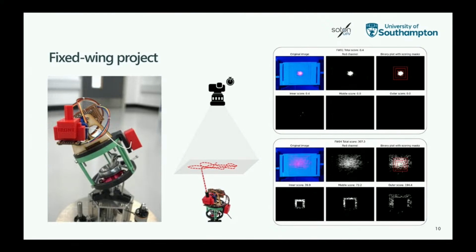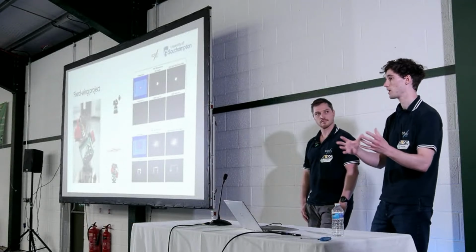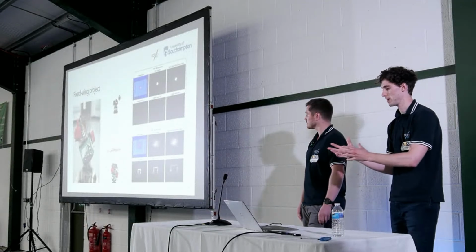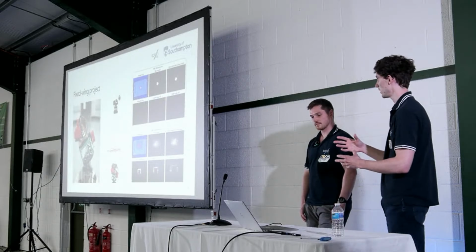That's because when we do the testing to get a quantitative value for the student's grade, we put a laser pointer into that gimbal. That points up onto a sheet of paper, and then we take a long exposure photo, 60 seconds, from top down, and then we run a simulated flight with the tilt table. Obviously, the students are watching at this point, so they get a really good visual representation of how well their system's working, how well it's going to stabilize the camera once we have it on the aircraft. And then we use computer vision to grade the individual images.